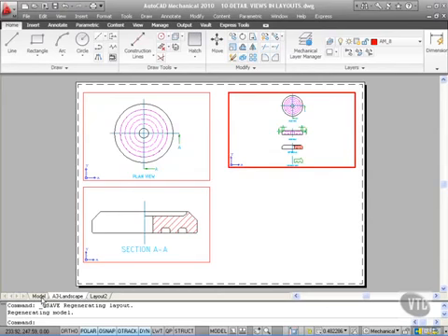Now the model tab itself still has all of the information in it. So what's happened here in this current viewport, the live one here, is that somebody has done a zoom extent so that you can see the extent of the visible drawn objects in the model tab in that particular viewport. Now what I'm going to do there is I'm going to set up a named view in that viewport first. So that viewport is current, it's live, you can tell that by the bold outline, and as you can see, look, the crosshair appears only when I'm moving over the viewport there.